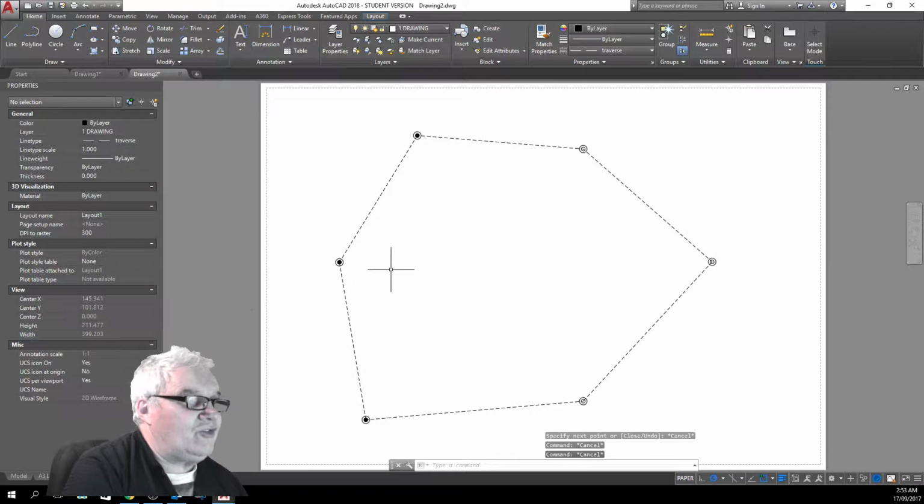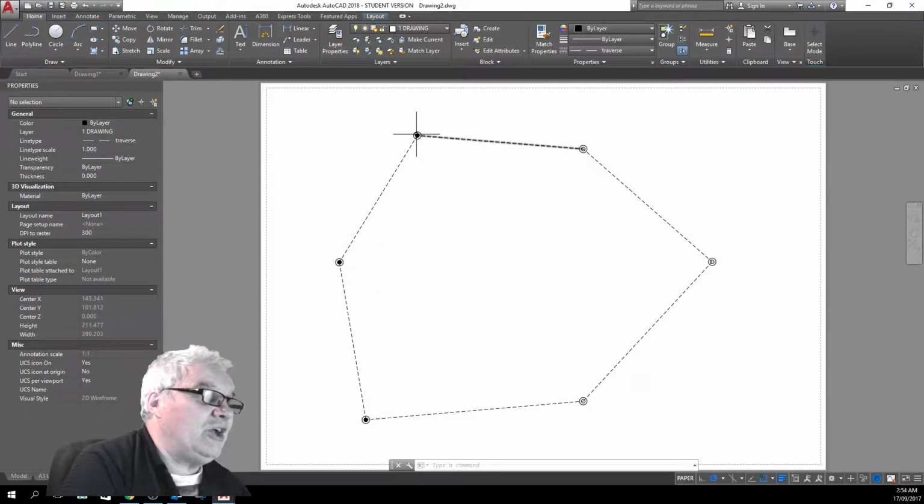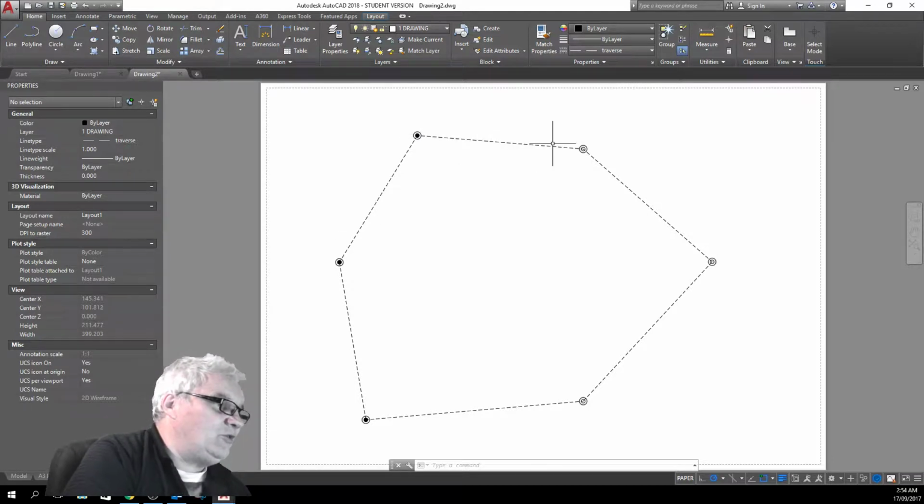Let's say we started here and set this one as the origin of bearings, and then we checked onto that. Then we would go to here, set this bearing, measure that, make sure it agrees, and measure this through to here.